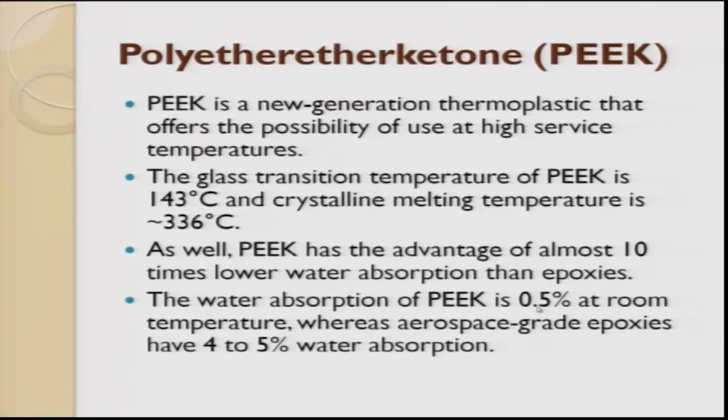And again, you should now be mentally clear, it is not one property you choose to pick a polymer. You always look for multiple properties. Depending upon your requirement, you have to start using it. For example, in aerospace, we look at low water absorption, low smoke, lightweight, and slightly higher temperature. So all these properties are thought of, and then you choose a polymer for it.